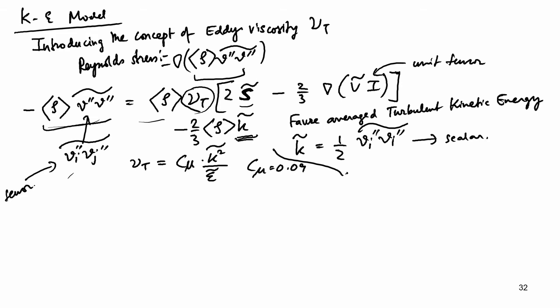So, we need closure for those, and those closures are essentially provided by the k epsilon model, because you have k and epsilon here. So, we have a governing equation of turbulent kinetic energy which can be exactly derived, just like the way we derived it in the previous class, though that was for constant density flows. This is a little more complicated, but the basic essence is similar.